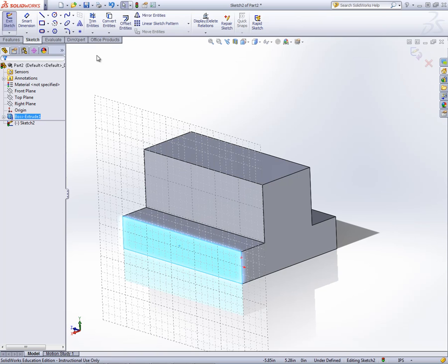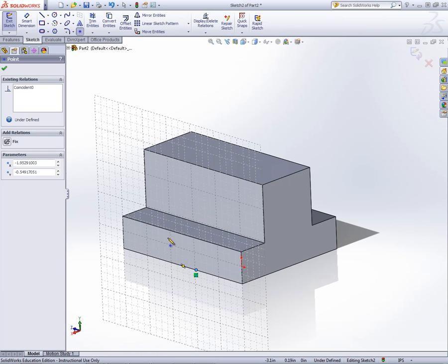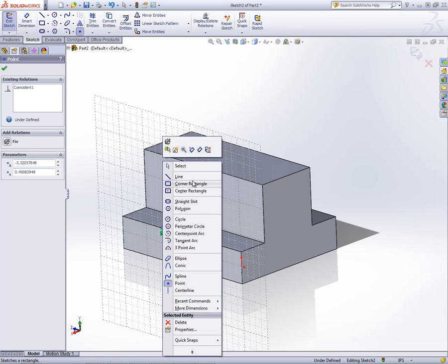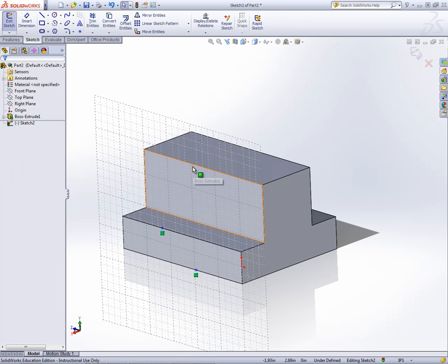So we'll move our cursor to the upper left portion of the screen. Right underneath the little A is the point icon. We'll left click on Point. We'll bring our cursor down. Just float our cursor along the bottom line somewhere. Don't hook it to the midpoint because we're going to dimension it. So we'll left click right there, and then we'll place another one back here. Again, don't hook it to the midpoint. Then we'll right click, left click on Select.